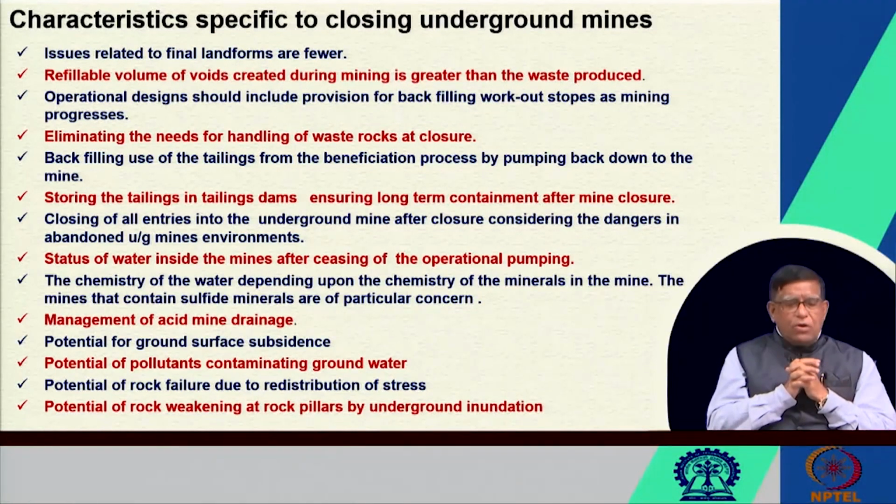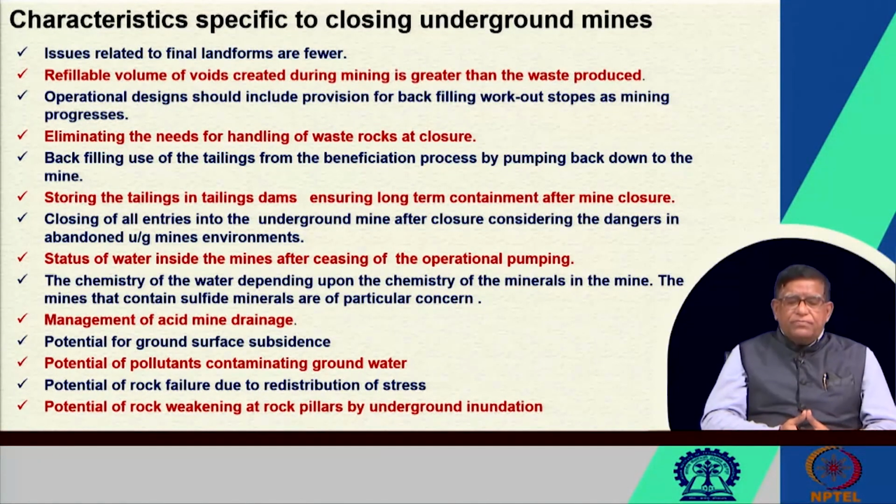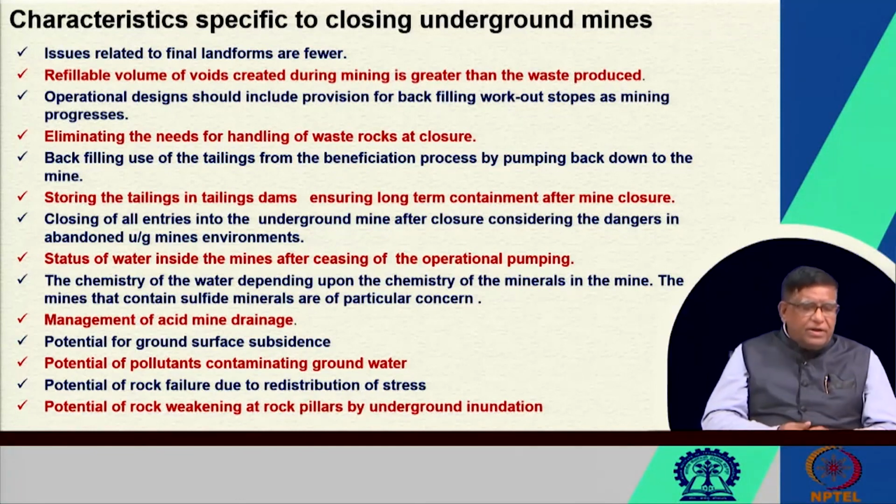Now, when we think of closing underground mines, different types of issues will come. First, what type of landform will come over there, then what exactly the voids will be left, because if you do not backfill it, then subsidence can take place and it can create problems. Many sinkhole formation issues have occurred in different countries because mines were not properly closed.